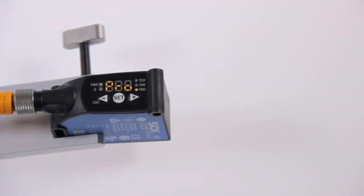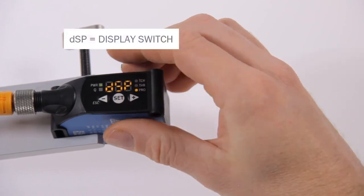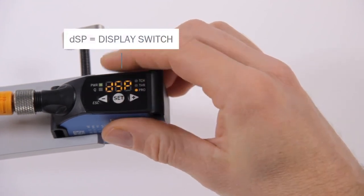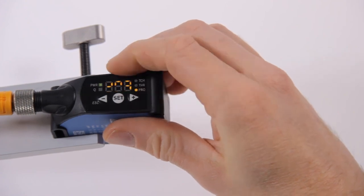Display switch. In some applications, the sensor is mounted in a way that the display can only be read upside down. The display switch function allows turning the display by 180 degrees. Use the plus and minus buttons to navigate to the menu item DSP and confirm with set. Now the display alignment can be turned and confirmed with set.